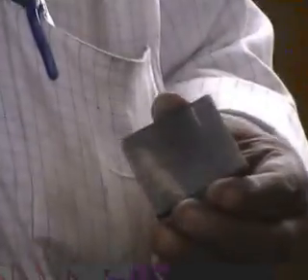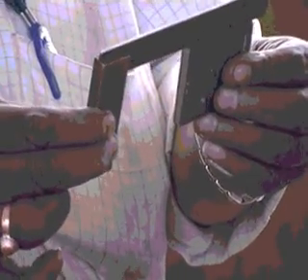Now we have to make a 45 millimeter square piece. First we'll file it to make the piece straight. To check whether it is straight, at 90 degrees, we use a tri-square. Now how to use a tri-square? We keep this surface attached to the tri-square, and against light we check if there is any gap on the surface.